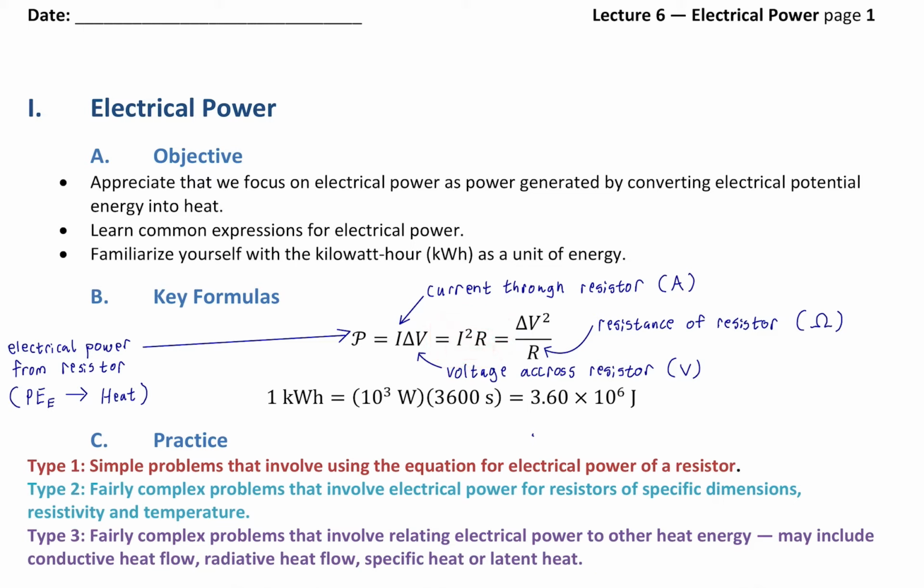But definitely the most common that you'll see, and you'll almost take it for granted, is fixed voltage. So you'll think of resistance as being something that decreases power. As resistance goes up, power goes down. Okay? But again, to be fair, that is only for a fixed voltage. By fixed, I mean unchanging.